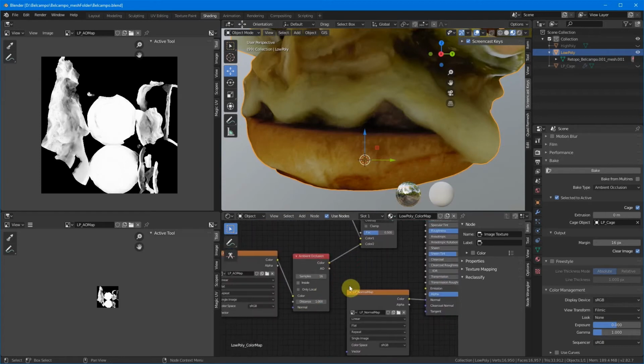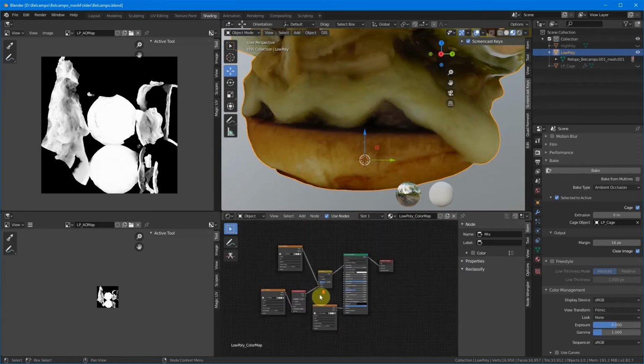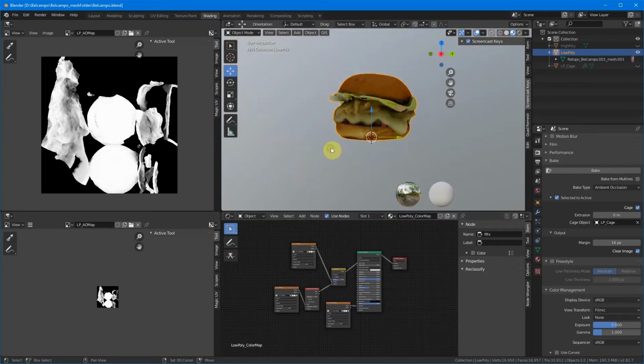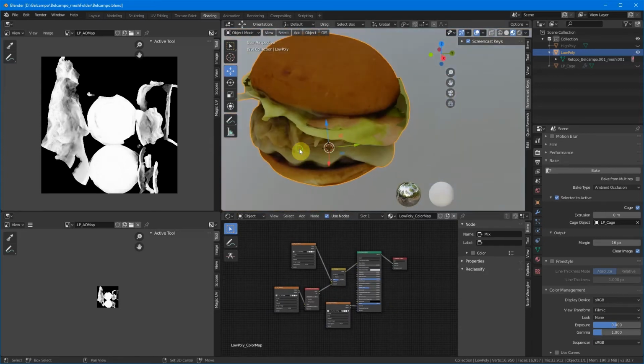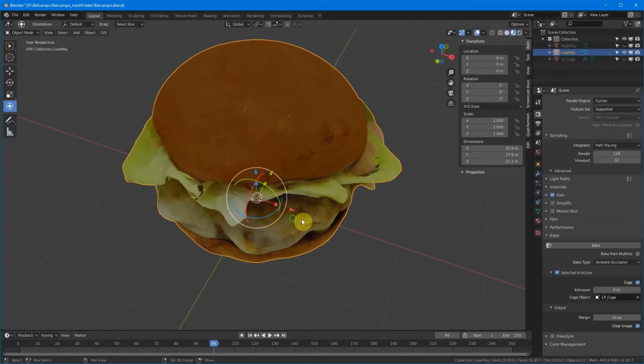But how can we see the difference? If we use Control and right mouse, cut the noodle, cut this line, we can see a very subtle difference. See, this has become brighter, right? See, it's dark. It's brighter. It's dark. It's bright. Because the ambient occlusion map helps the render machine to understand the light. This is pretty much it for the texture baking.